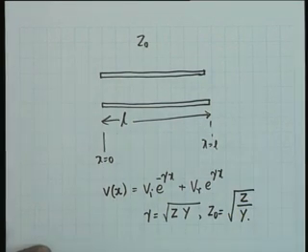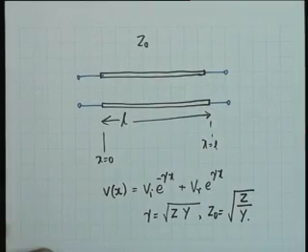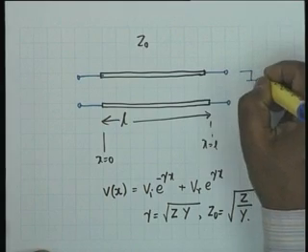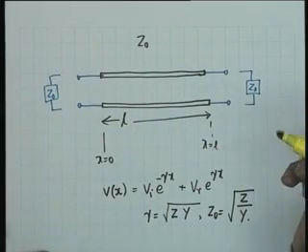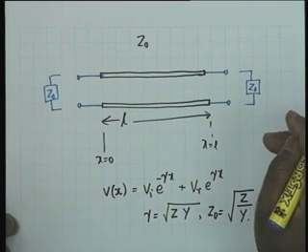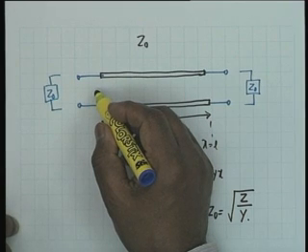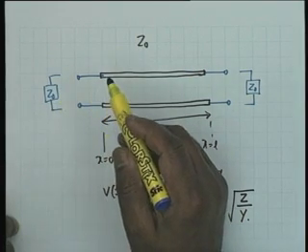Now let's find the scattering parameters of this two port considered as a black box. These are the terminals, and let us say the terminating impedances both are Z0, the characteristic impedance. Then the reference impedances at both ports are Z0. All right. So if we want to calculate S11, we terminate this in Z0 and find the impedance here. What is the impedance here? Z0, right? And therefore the reflection coefficient, driven from a source of impedance Z0, would be 0.